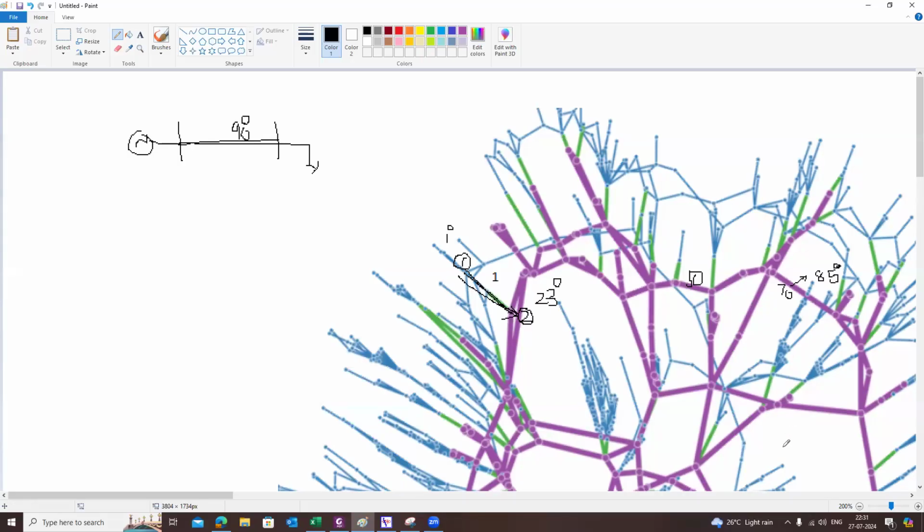Any questions? Sir, is there any reference for this angular difference to be used for the utility? Yeah, you can refer to the Transmission Planning Criteria by CEA, the Central Electricity Authority. There is a document called Transmission Planning Criteria, which was updated in 2023. You can refer to the document that is available on the CEA website.